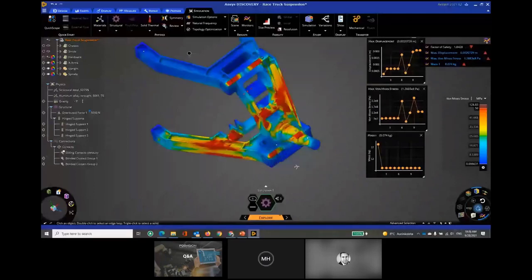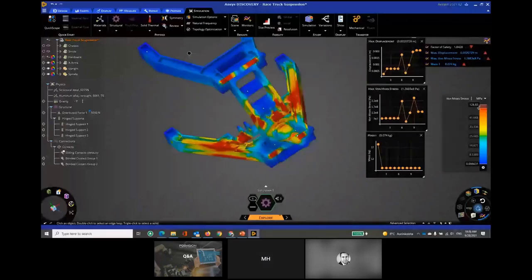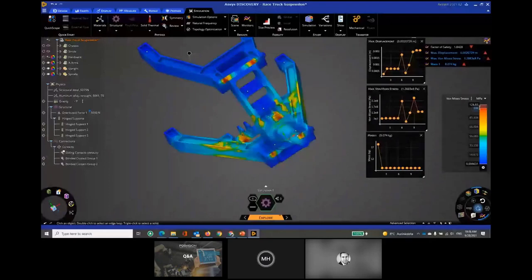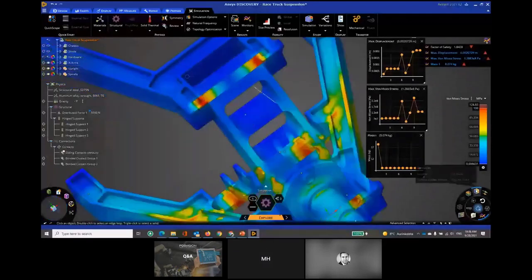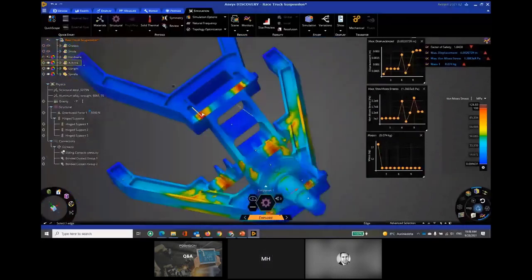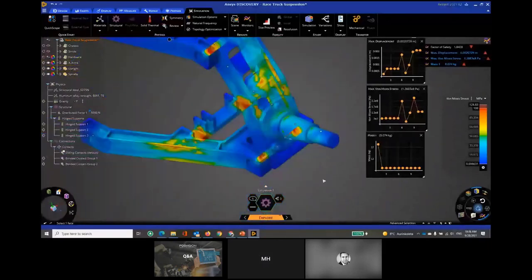I have to make some other number in here, otherwise this is not really readable. Now you will see this bolt, which is covered by other geometry, just because I have this show highest value filter on, so I can see inside the model where my highest stress values are. So in these joint bolts, stress levels are quite high.